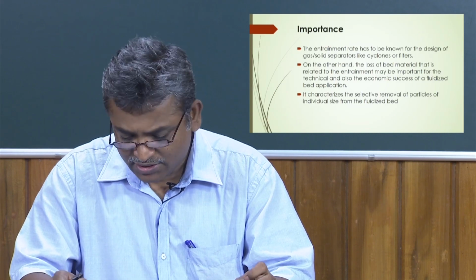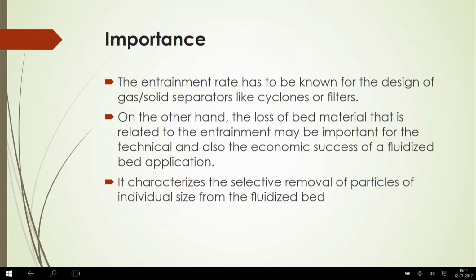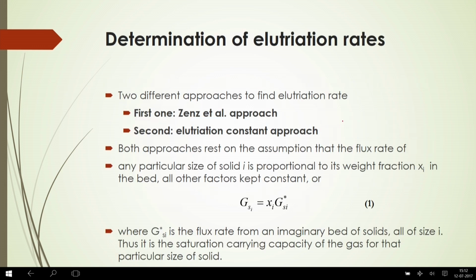And it characterizes the selective removal of particles of individual size from the fluidized bed. If you are going to segregate the particles from this bed, then there will be a selective removal of the particles of individual size from the fluidized bed by this elutriation mechanism.